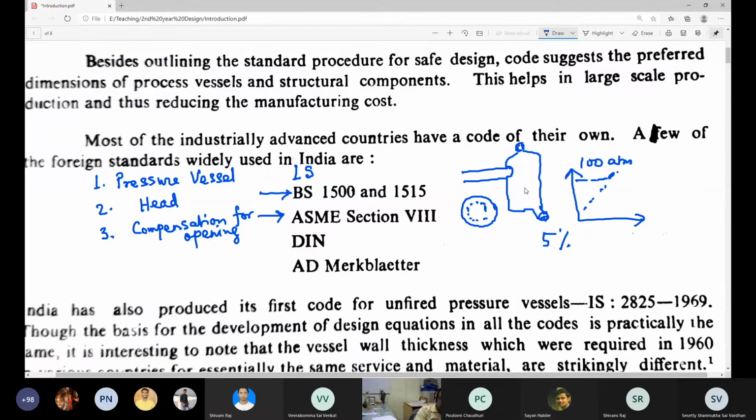As far as this pressure vessel is concerned, the material that was present here, which you removed so that you could make a hole for the pipe to go in, was supporting this pressure vessel. That material is now gone, so one has to put an additional layer. You may see an additional layer surrounding it, more like a circular pad. That has to be provided so that this opening area is compensated. What should be the thickness of this pad, what should be the diameter of this pad, is something which we will design.